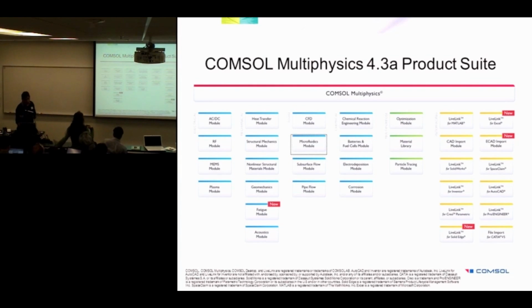So especially for the microfluidics community, we focus on the microfluidics module. That's the module which we'll be adding on to our base package, which is on the top, Comsol Multiphysics. But sometimes you might also need heat transfer if you are working with a bioheat transfer equation. So you might need the heat transfer module, or if you are working with some other kind of two-phase phenomena within microfluidic devices, you could go with a CFD module. So those add-on packages could be added to the microfluidics module. And then if there are more sophisticated surface reactions or homogeneous reactions, you can choose chemical reaction engineering.